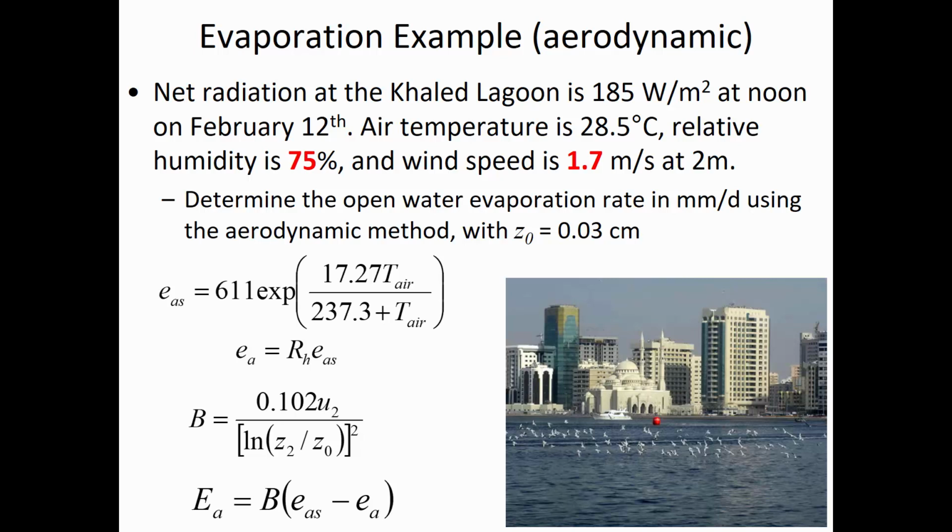So water will be a small fraction of the overall pressure, but this is saturation. At most, it's going to be 3893 pascals. Okay, so the relative humidity is 75%. That's something that you can measure with just a meter that you could pick up from Walmart. You know, relative humidity meters are kind of a dime a dozen.